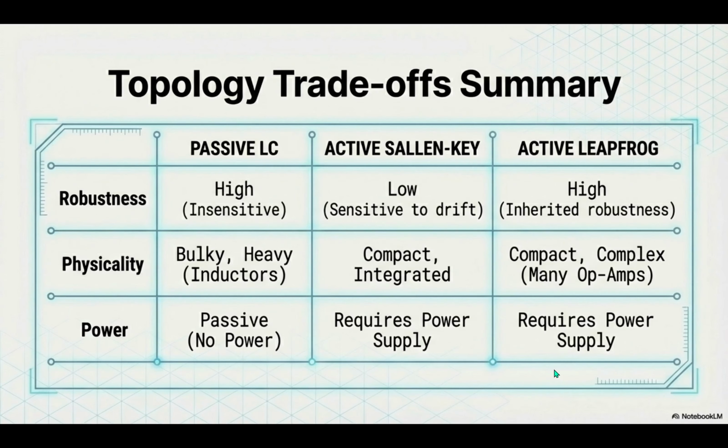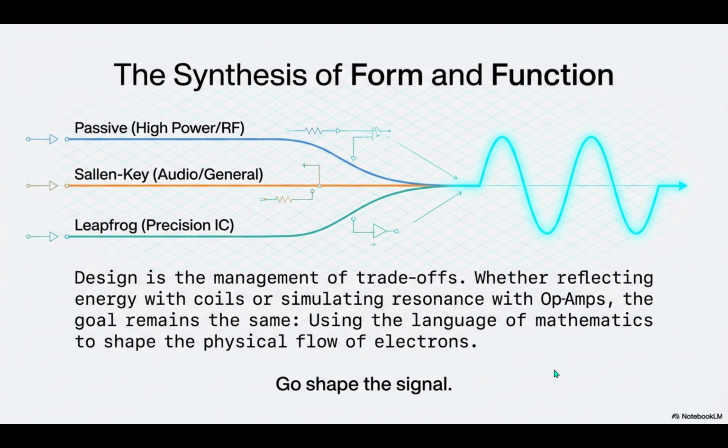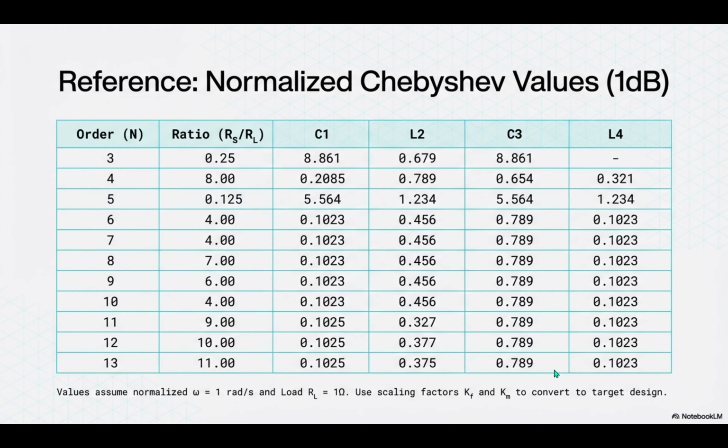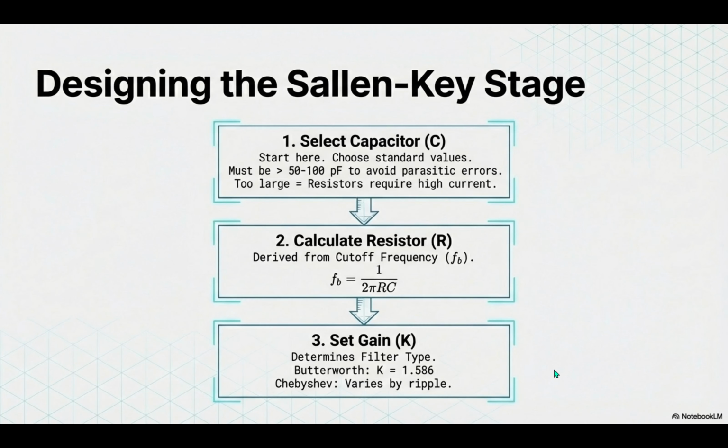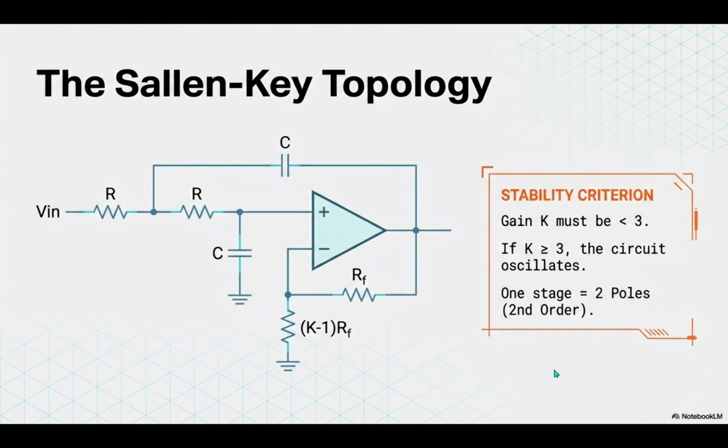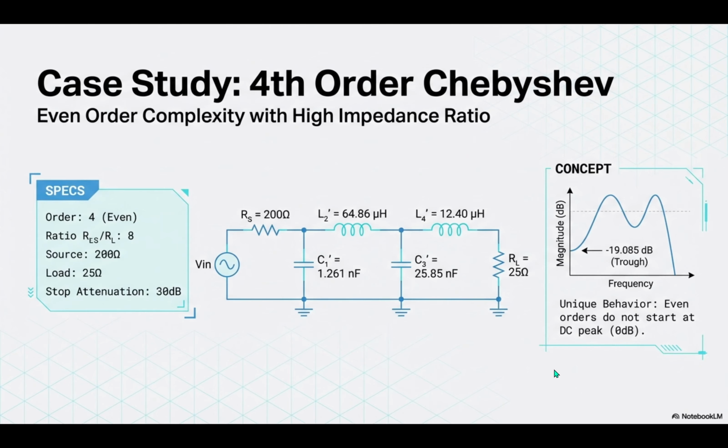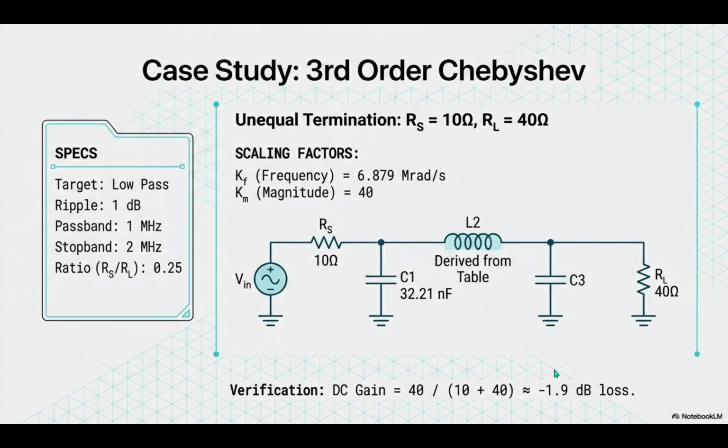Perfect. Yeah. Then you connect it to a speaker or another amplifier stage. That changes the math. Completely. That new component has its own impedance. It draws current. It effectively changes the resistor values in your original design. You've changed the variables in your equation just by plugging something in.